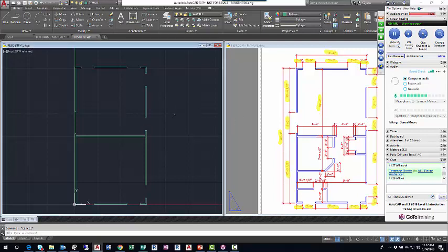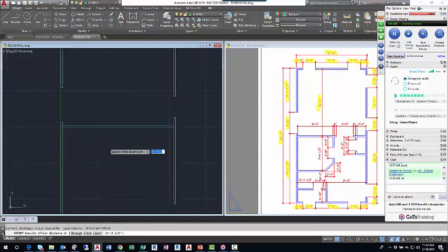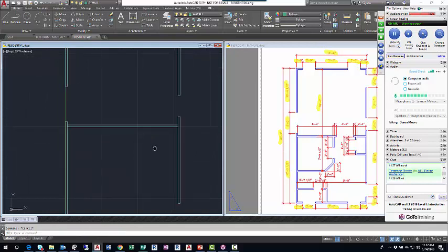All right, so up till now, every time I've used the offset command, I've restarted offset to plug in a new distance. This time I won't do that. I'm going to go offset. I'm going to zoom in so you can see this. Well, I mean, the prompt won't get any larger, but the lines will be a little bit better size. Offset, 8 feet 3, enter. I'll left click that first vertical line, move right, and left click. So there's my first offset.